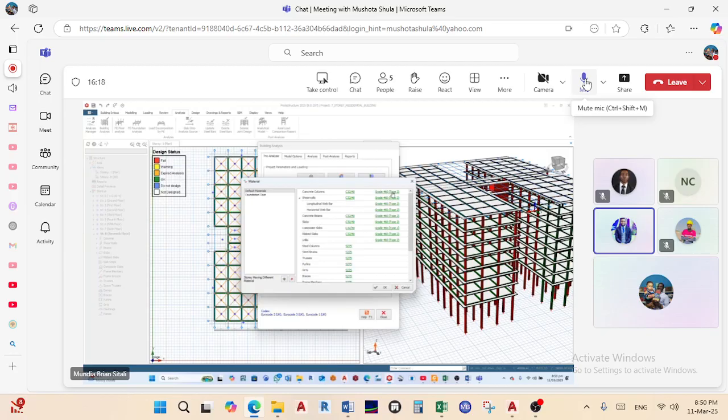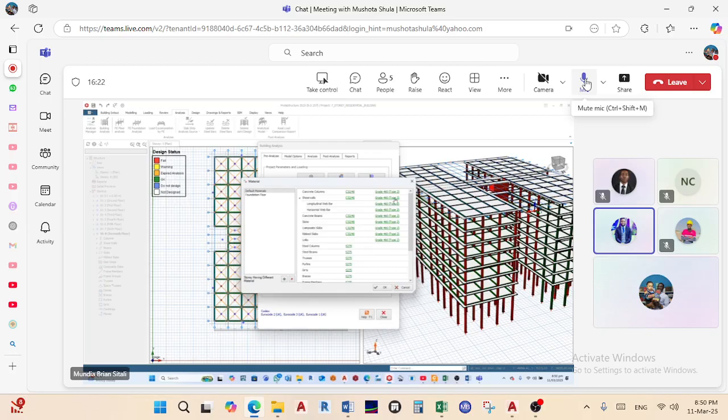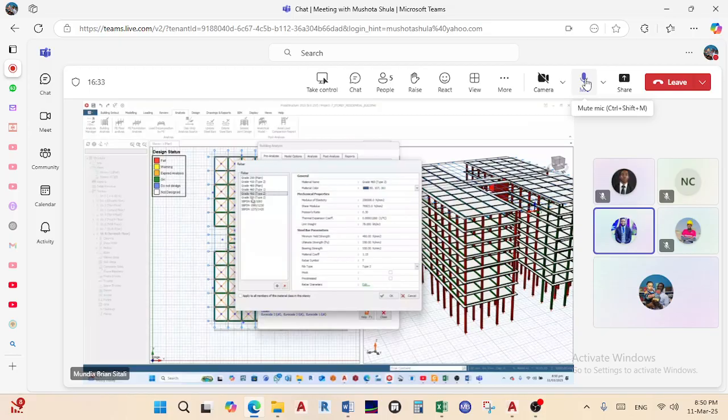Similarly on the steel, okay? If say for instance, already here you can see that it's 460, yeah? So if I say I want to adjust it to 500, grade 500 steel, type 2. So I'll say I want to adjust to 500, okay? Then I'll say, instead of this just changing for this particular one, I'll click this one so that the same setting can apply to all the member classes in this story.